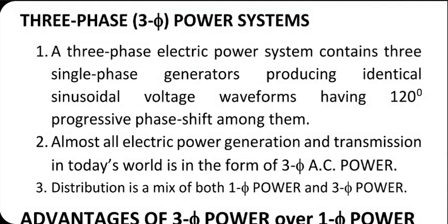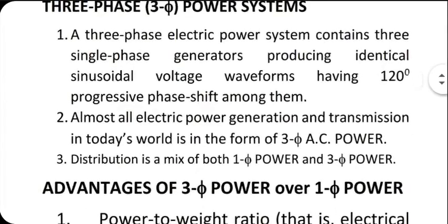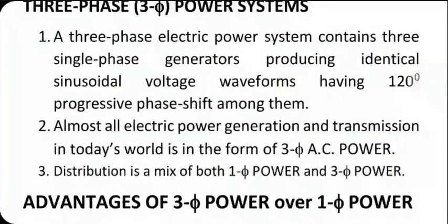On the distribution side, transformers are going to give you both three-phase and single-phase voltages. And depending on customer requirements, you may want to give a different thing. Sometimes in the same factory, you will need both single-phase and three-phase supply. Even in homes nowadays, bigger equipment needs three-phase supply. Many homes also are demanding three-phase. So based on that, distribution challenges are very different. A mixture of three-phase and single-phase is what distribution is all about.